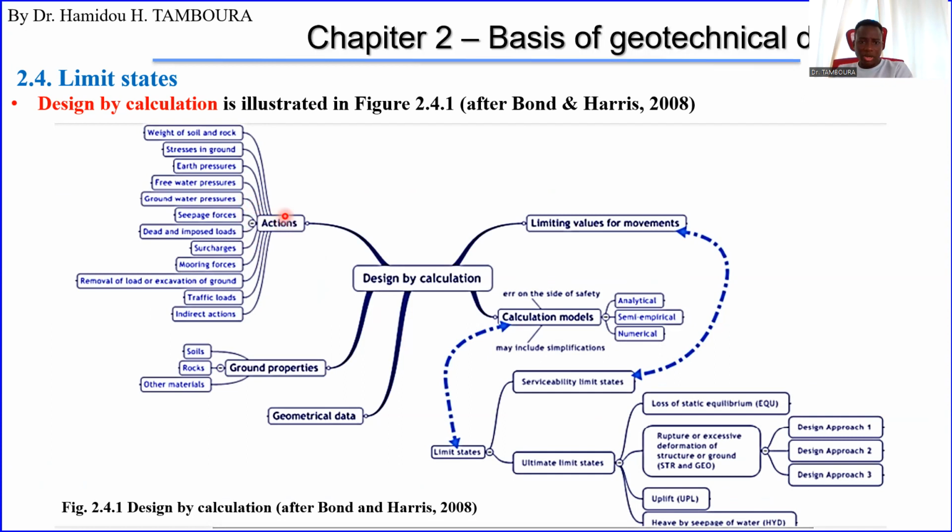So as you can see, we have here actions coming on your structure. For example, you have weight of soil and rock, stress in ground, earth pressure, free water pressure, groundwater pressure, seepage force, dead and imposed load, surcharges, mooring forces, and we have removal of load, because when you do excavation, you are removing load.